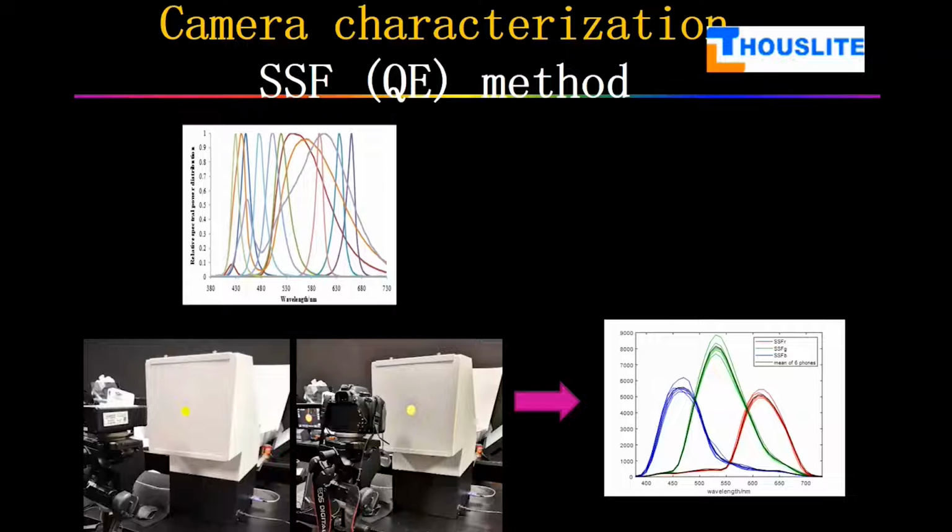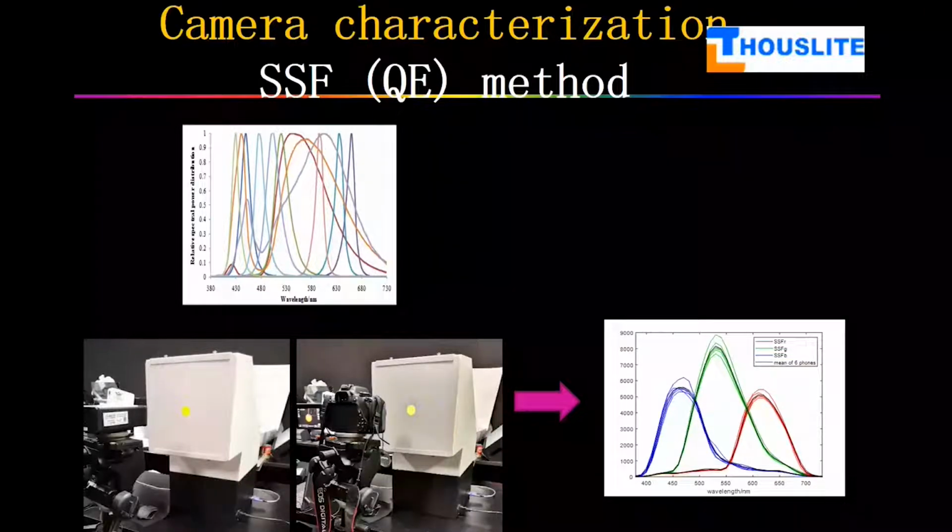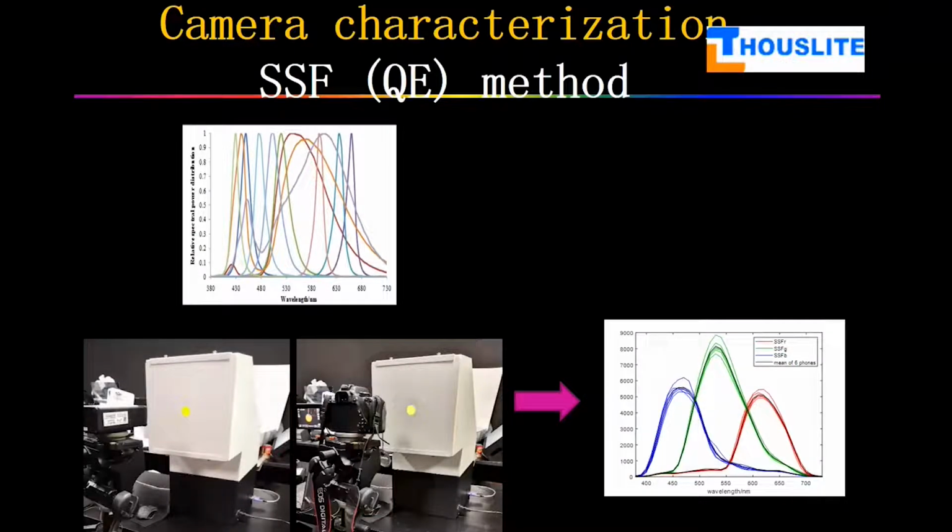At the bottom right, look, this is what is being measured. What is the goal? It's our work: the red, green, blue representing the eye's response of the camera. So when we do the calibration, we don't need to go through the matrix. We can just go through the spectral, 31 by 3. These are what we call the SSF. So every camera in the production line gets its own SSF, and it will reflect the individual performance. Next, please.